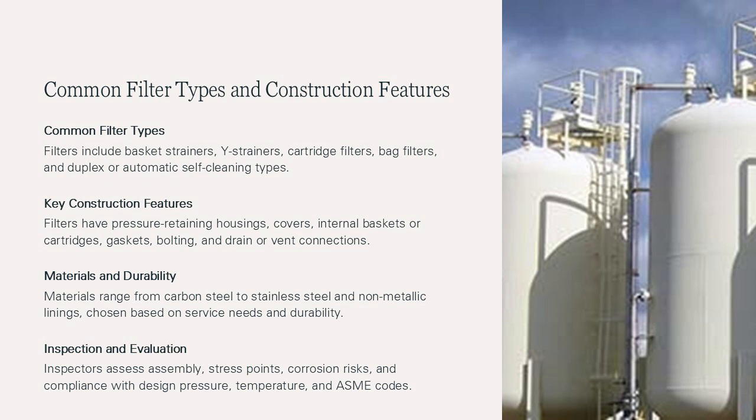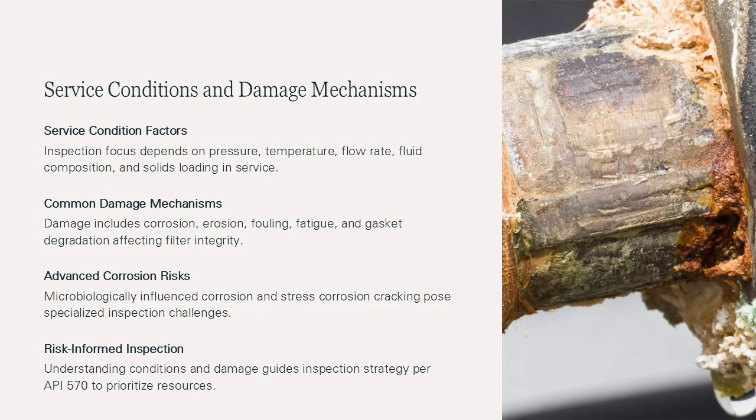Knowledge of original design pressure, temperature, corrosion allowance, and ASME code of construction is essential for evaluating current condition against allowable limits. Service conditions play a major role in determining inspection focus and frequency for filters. Inspectors must consider operating pressure, temperature, flow rate, fluid composition, solids loading, and process upsets.